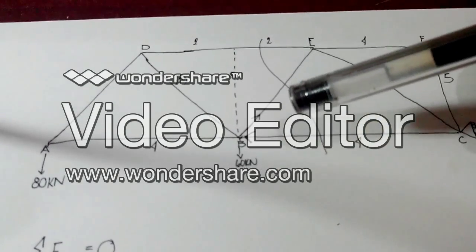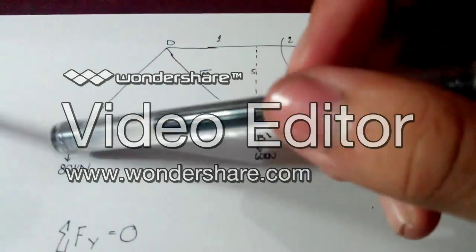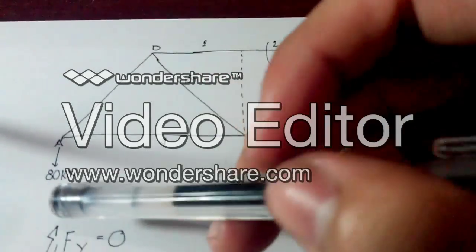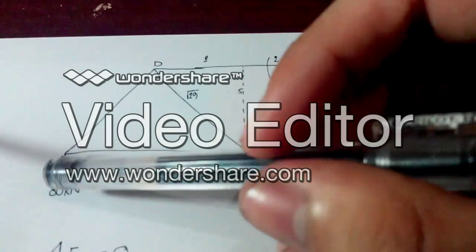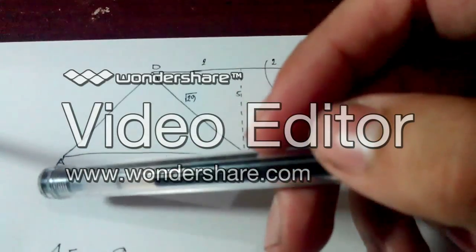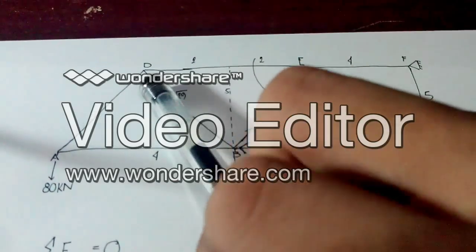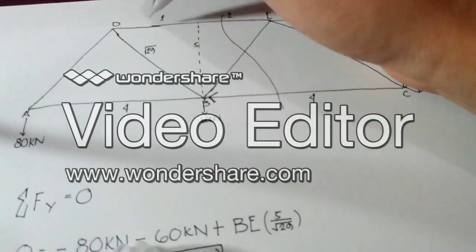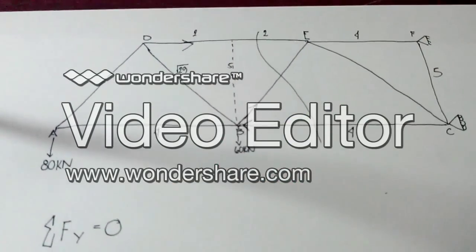So the forces that we can use are the force on A and the force on DE. The 80 kilonewtons is negative because it rotates counterclockwise. We need this DE to be positive, so it's tension.